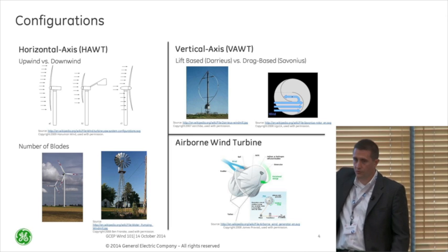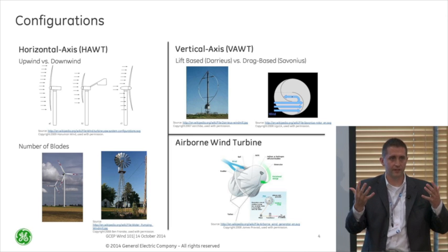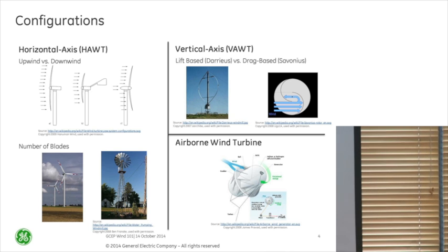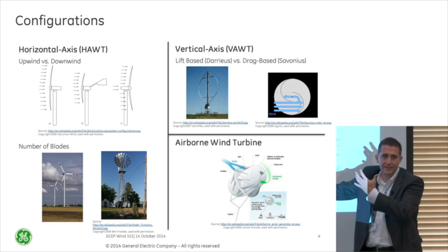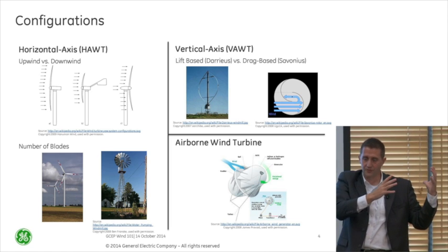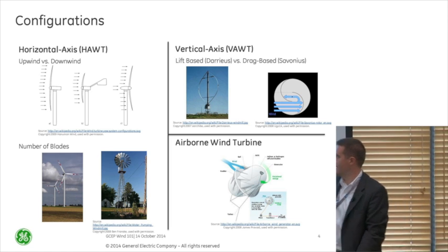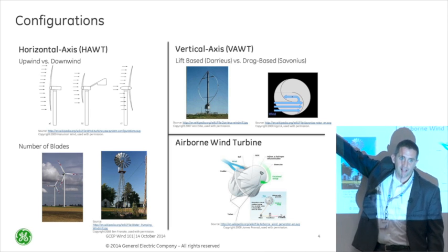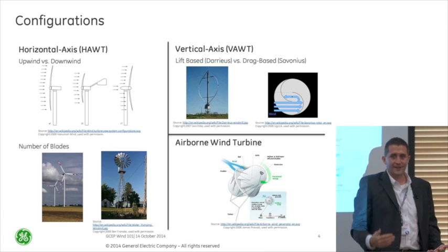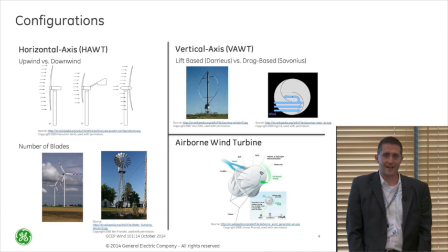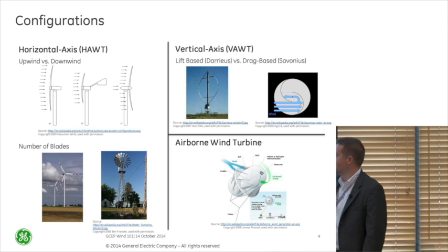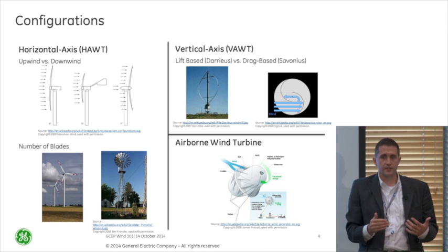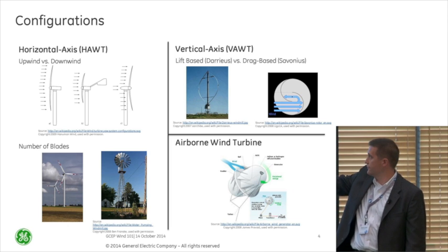So you can really have these in two different ways. You can have the blades in an upwind configuration or a downwind configuration. In an upwind configuration, the far left up here, you see the wind coming in, hitting the blades first, and then it goes to the nacelle and the tower afterwards. That's typically what you see. Big important thing on blade design is how much these blades bend. So how much tip deflection do you actually see, because you don't want to hit the tower, right? These blades spinning around, if that thing hits the tower, the whole thing goes down, and that's not really good for a product. So that becomes a really important design criterion for wind blades, is how much deflection you really see.